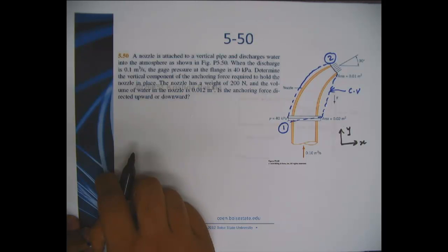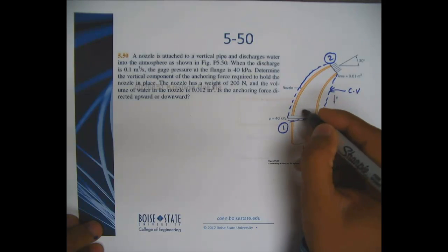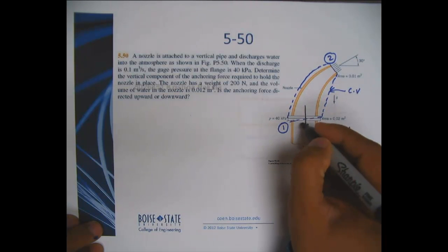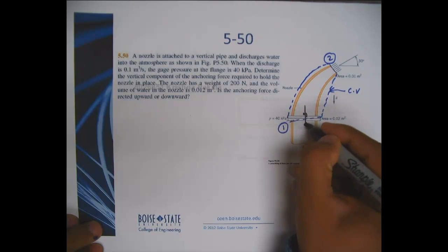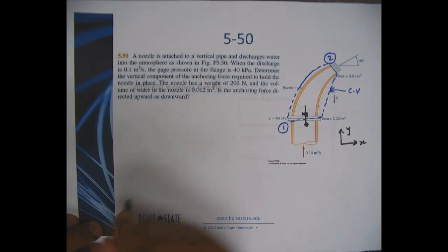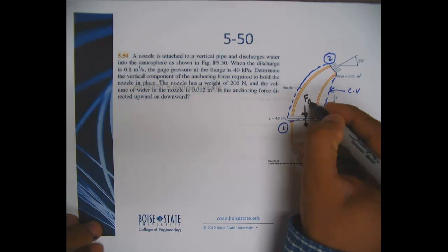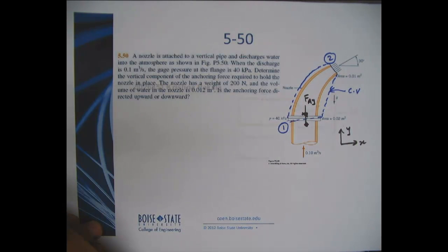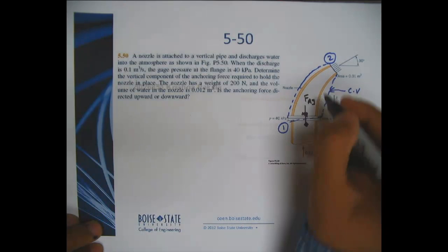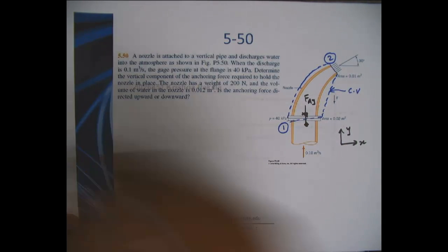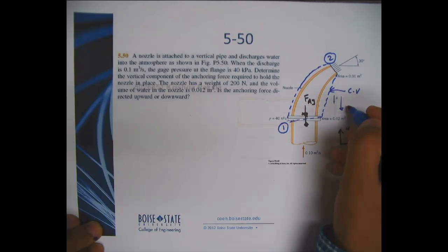Now we are interested in finding this anchoring force here. We should probably draw it at that point, which is some FAy. So that's your anchoring force, and you know that there is this weight of the water. I'm going to represent it here just for clarity. So there is weight of the nozzle, and also there is weight of the water.